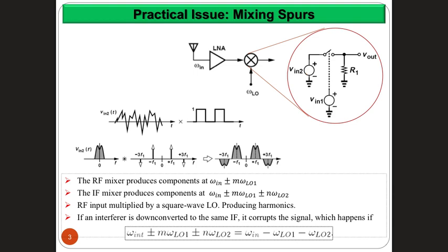Remember from your signals and systems, if you have a periodic square function, the frequency components of this periodic square function span an infinite number of frequencies, right? It becomes a Fourier series summation of the fundamental frequency, which is the basic frequency here, and then another component at double that fundamental frequency, and then another component at triple that, 4 times, 5 times, and so on. These are called the harmonic extensions until infinity. You add until infinity. Okay?